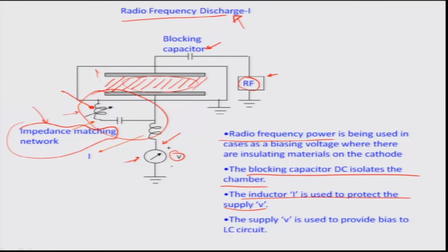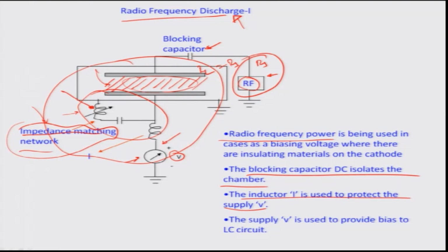Therefore, the impedance that this capacitor plate set would offer to an AC or RF signal would be really varying. So, we need to keep changing the overall impedance in this whole region, so that this RL, or the load resistance, could be made always equal to the source resistance of the RF power right here, for the maximum power transfer from the RF voltage source into the system. That is the reason why we have an impedance matching network, as you can see particularly here.